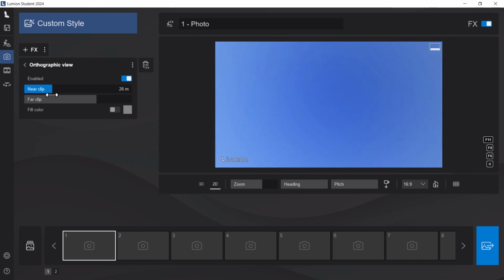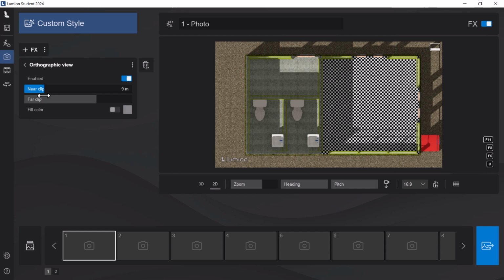Now, the other thing is the clipping options. If you remember, you can clip away the model. See how the poche goes away when I clip farther into the wall. And this is just kind of an annoying, glitchy thing that Lumion seems to render the inside material of the wall when it uses its own clipping planes. So you'll want to not use those clipping planes. You'll want to just use the section box.